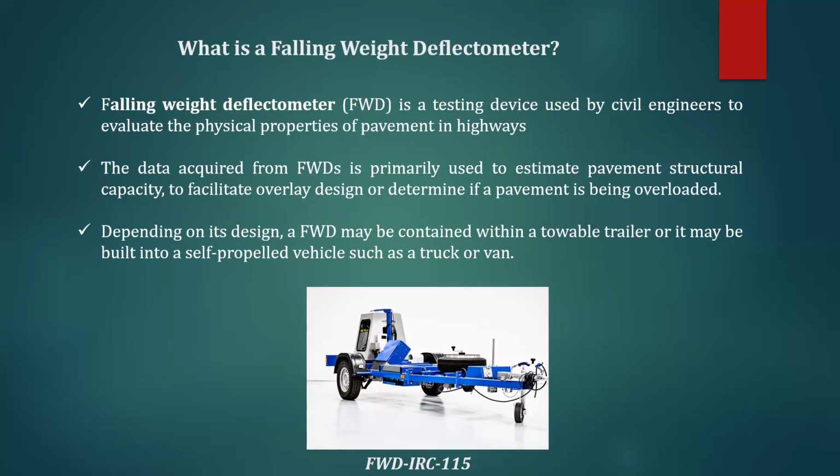For the surfaces which have some rebound deflection, which are elastic in nature, we take into consideration that rebound elastic strain, and we define that as a resilient modulus. So the data acquired from the falling weight deflectometer is primarily used to estimate the pavement structural capacity.